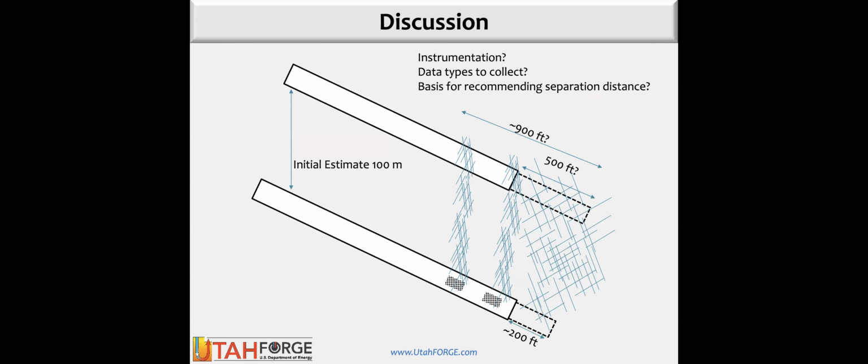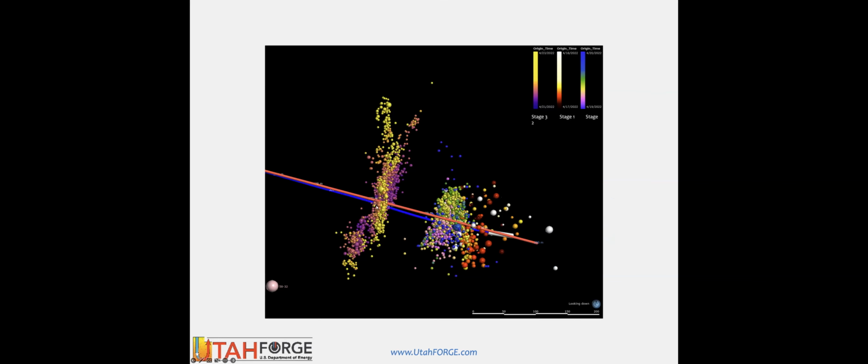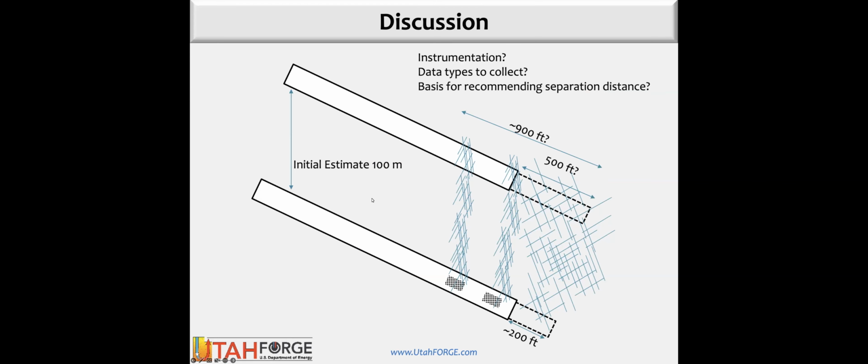As a reminder, last time we had this same slide, but a little bit different, and we had some comments on it. Essentially the initial estimate for 16B was to have a 500-foot open hole toe. If we look more closely at these plots, these are once again in meters: 100 meters, 200 meters, 300 meters up the borehole. Our initial 500 meters essentially put the third stimulation fully behind casing, the second one mixed somewhat behind casing, and the first stimulation somewhat mixed in between. That is still under discussion.